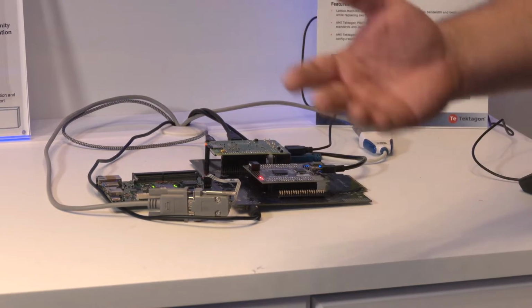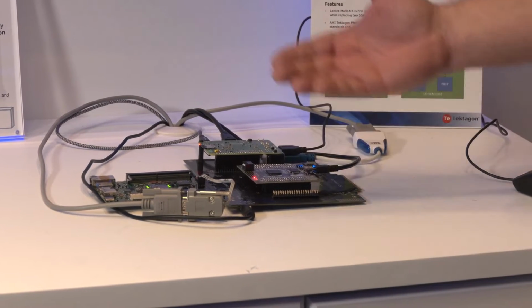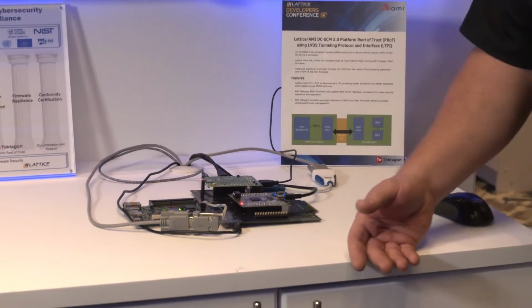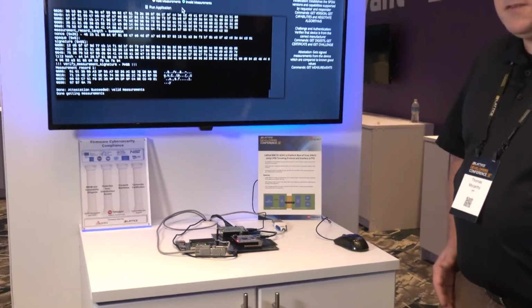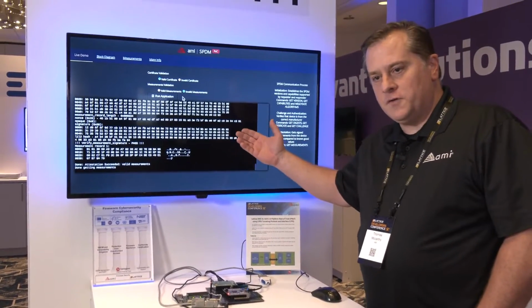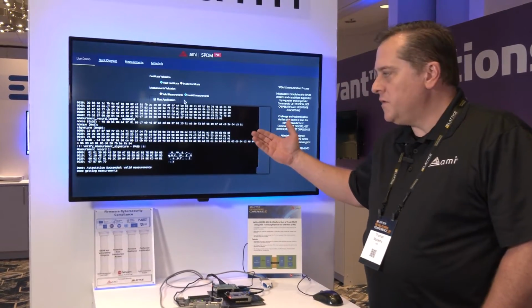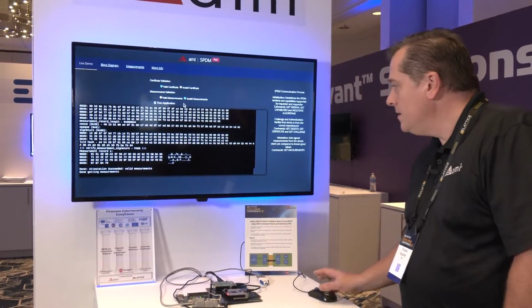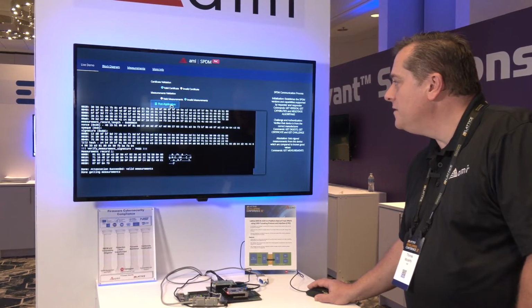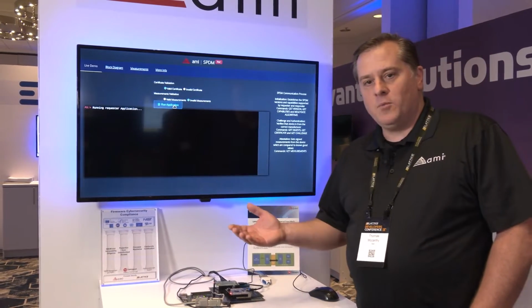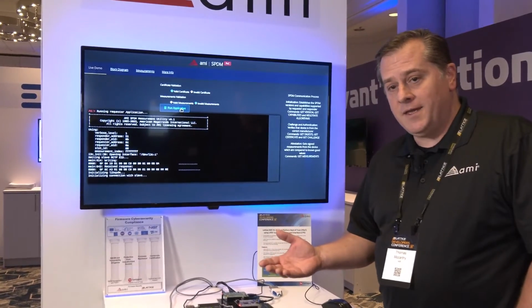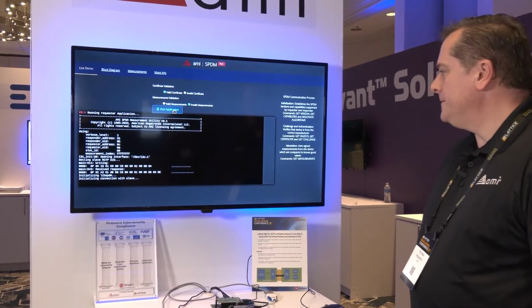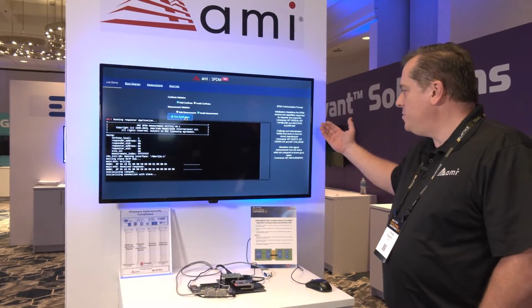And what we'll be showing is attestation of the BMC firmware, which is a key feature of platform firmware resiliency. But through our attestation, we don't just check the signature certificate of the firmware, but also we take measurements and verify that the firmware has not been corrupted. So in this case, we're presenting firmware that is going to have a valid certificate, but where the measurements will not be adding up. Initializing SPDM.